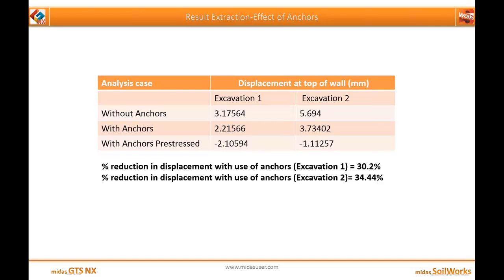Also, if you see the results for the pre-stressed anchor, you will find that it's coming negative in direction. Negative means in the negative X direction, that is the anchors with the pre-stressing have pulled the retaining wall back, that is into the soil. So as such there was no pre-stressing required for this particular excavation sequence.